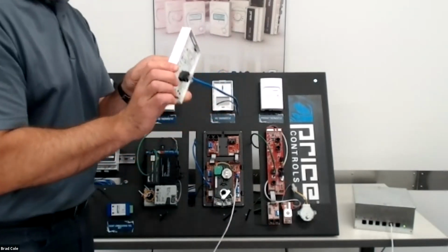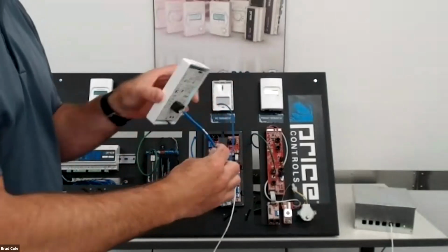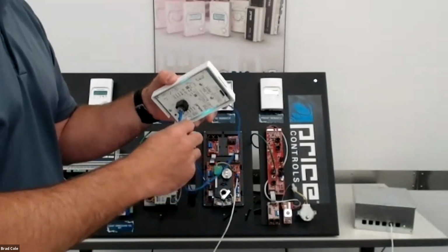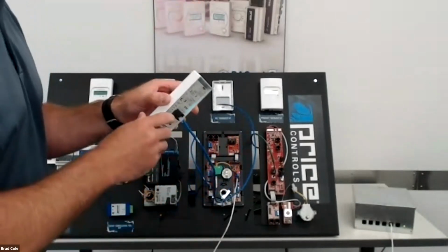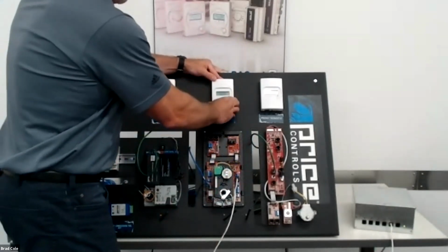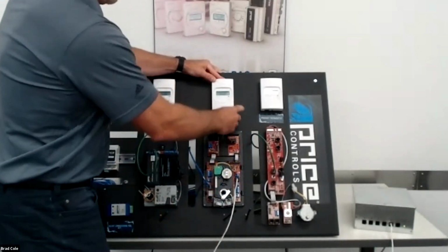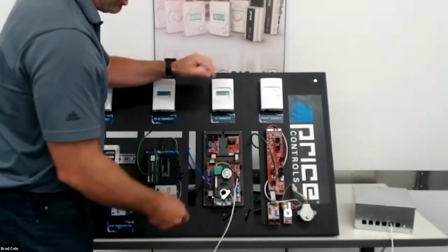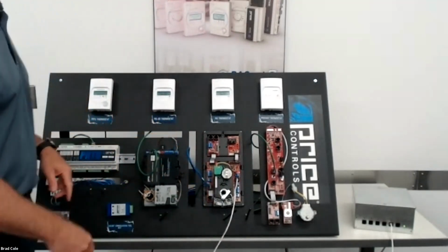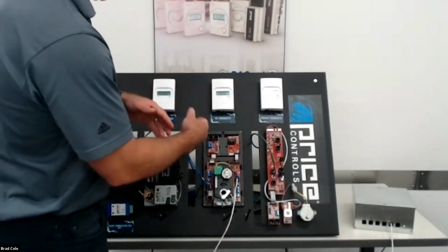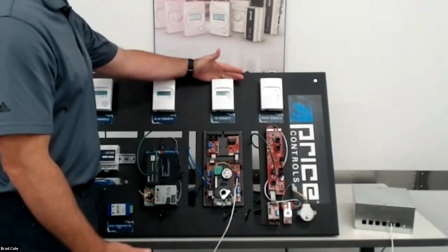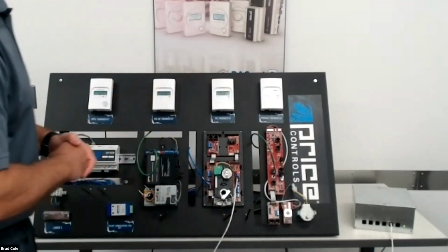But what I want to show you here, guys, is this simple Cat5 connection, RJ45 jack connection for wiring in a thermostat. You plug it into the back of the stat, run it down the wall to the J box or the electrical box, and then plug it in that way. And then up in the ceiling, you just plug it in this RJ45 jack here on the PIC controller, labeled T-stat. And you'll see that when you're in the ceiling. But anyways, it's in our manuals, but it's really straightforward to wire this thermostat and get it up and running. Again, no real wiring required.